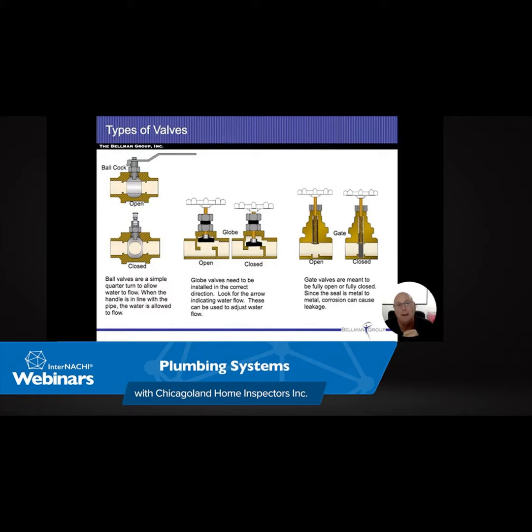The shut-off device failed, so the flame was on, staying on, and kept heating that water so much that it released on the pressure relief valve. The entire room the water heater was in, probably 50 feet by maybe 100 feet, was filled with steam, and that steam set off the fire alarm.